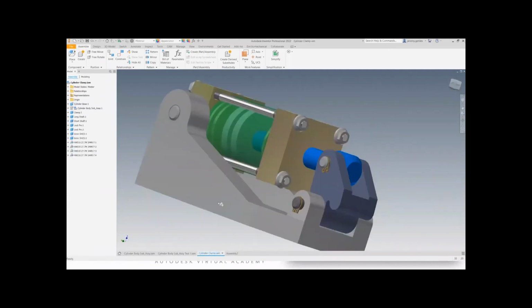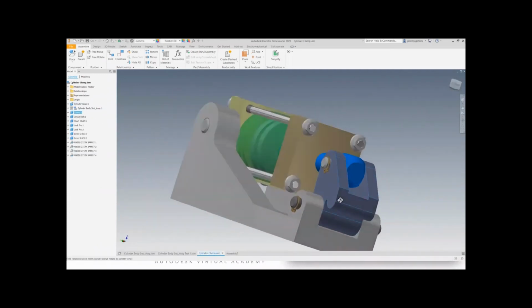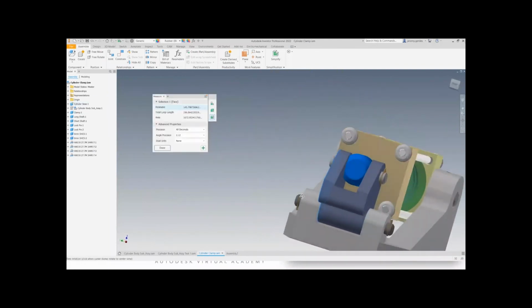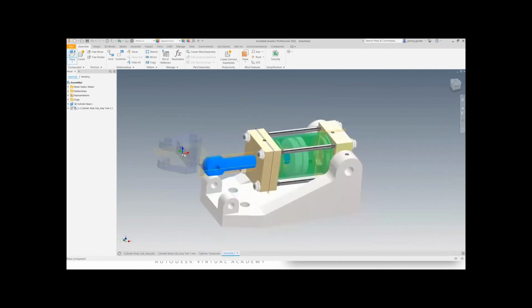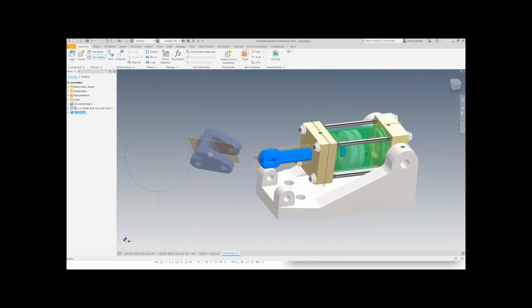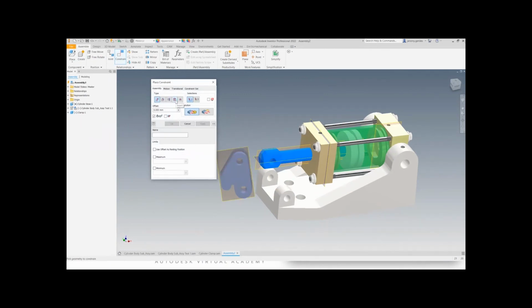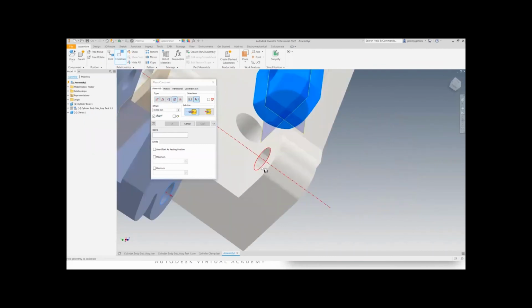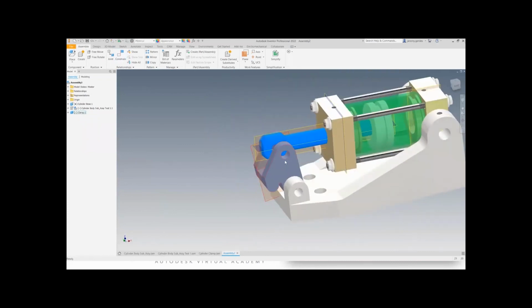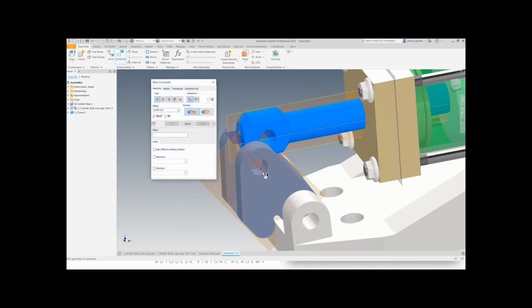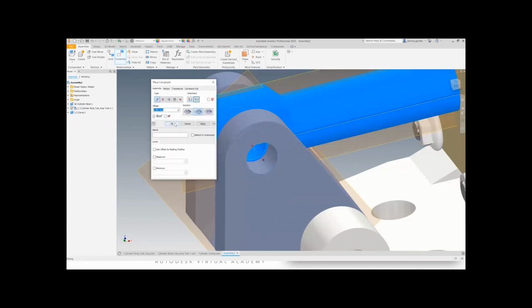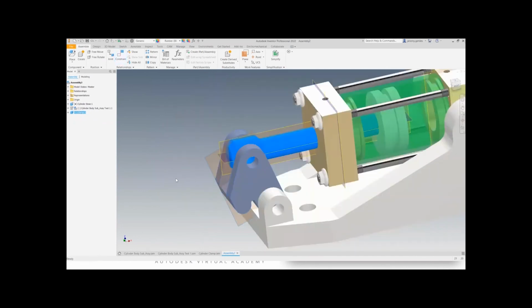So let's add another part to it. And the next thing they added was the clamp. Let's just see if there is any offset. I don't believe there is. Yep. So go back to place, clamp. Again, if I just hit G on the part, I can rotate it. So I can just get a better understanding of where it's going to sit. Hit C for constraint. Go to insert. Place it there. Then if I constrain it again to there, select that axis and that one. Hit OK. And it lets it have that movement.